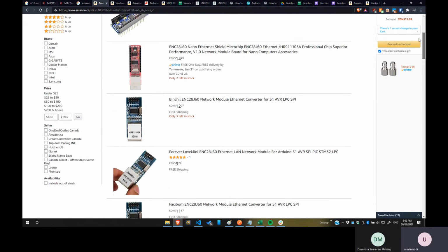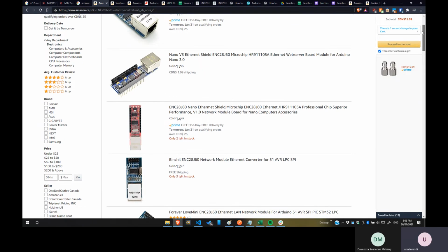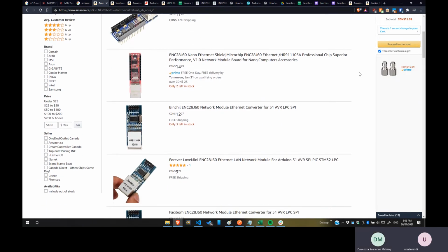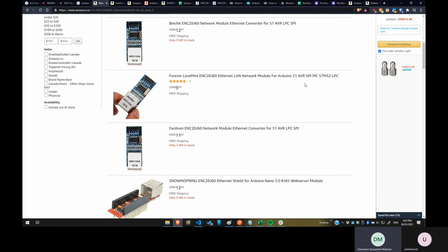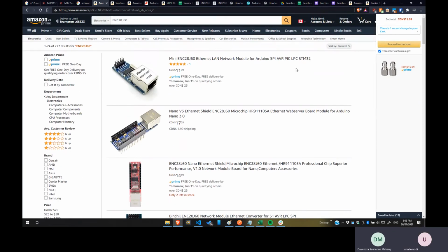Some of them are over spec to the point where, as Kiki and I have talked about, if you could exchange it for something that's a better fit for our spec, we'll get better precision with our data because the input ranges will be lower. The range for these thermometers is between -40 and 300 Fahrenheit. The thermometers are fine, but let's say we have a DC current sensor. The maximum current it could take is up to 500, right?